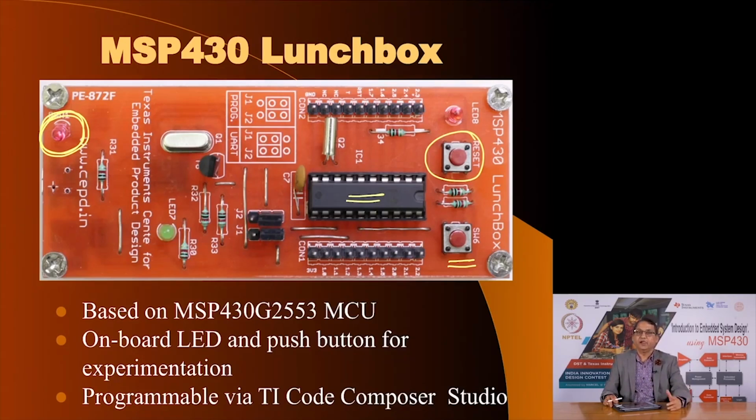If it was not there and if the system is not working, the user would be confused. Is it not working because the power has not been applied, or whether it is not working because the system is faulty. So, a power on indicator is a good way for that. You also have this crystal which is required by this CH340 USB to UART bridge. You also have a 32 kilohertz crystal as you saw in the previous slide. This is used by MSP430 for UART communication.